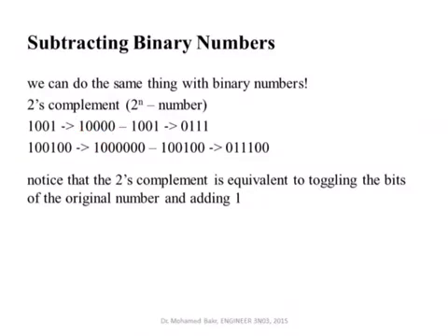It cannot be represented by only 4 digits, but by 5 digits. And then I will subtract from this 16, this 9 here that I have. So 1, 0, 0, 0, 0 minus 1, 0, 0, 1. Of course, I'll end up with 7, 0, 1, 1, 1. So this one here is the two's complement of 1, 0, 0, 1.